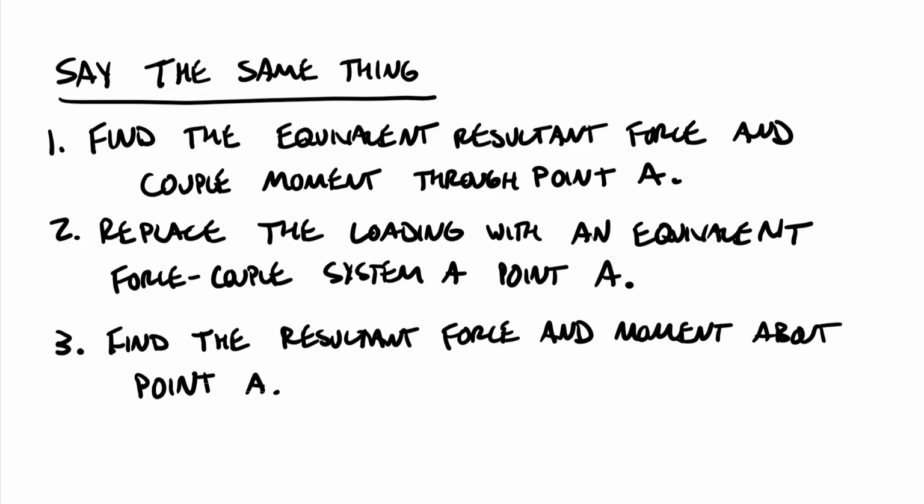Okay, so any of these three things, realizing that the reason they're using the first one here, this couple moment, is that once you find a resultant moment, you're basically saying that, hey, that's a pure moment around a given point. Now, not all force systems can be resolved into just a moment. It turns out that they need to resolve into a moment plus a resultant force.